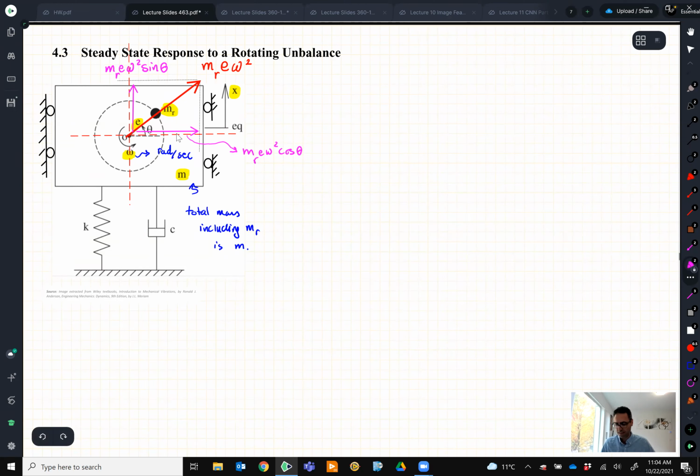It's a large value. So this is our free body diagram, and obviously I have the forces here from the spring and from the damping. The spring is Kx resisting the motion, because of the direction I picked, it is x, and this one is Cx dot.